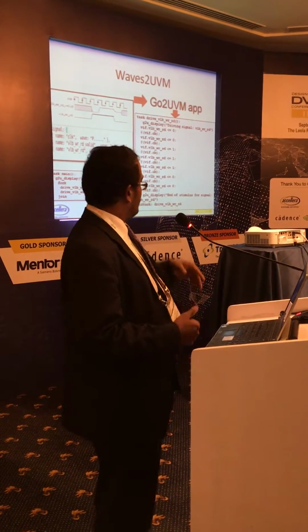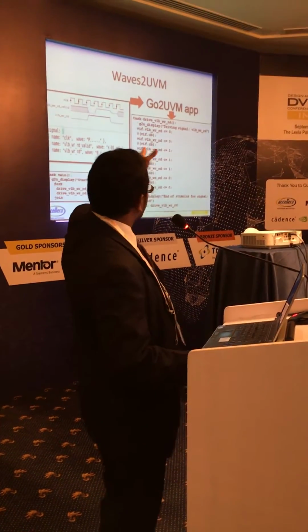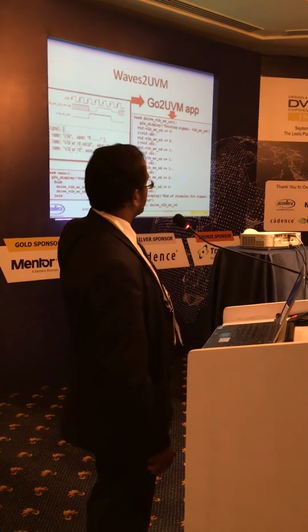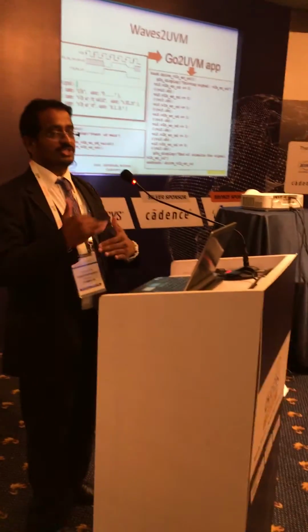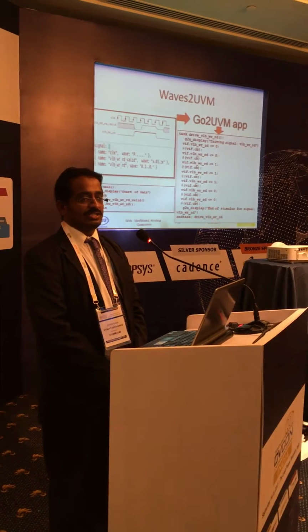But of course, be careful, because it's generated code. We are really tracking clock by clock. The moment you add, let's say, a delay at the 4th line, everything else gets delayed. You need to be aware. It's not parallel, it's sequential code. Once you know that, you can modify it, yes. But it doesn't directly support it.